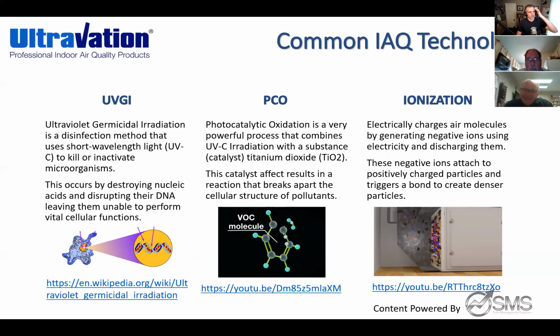So PCO, photocatalytic oxidation. We primarily use this heavily in the residential space, but it is actually available as options on our commercial stuff that I'll show you later as well. The biggest wake-up call here is a lot of people think everything's the same. They think it's UV light and you're done. Well, it is important to let people know, especially on the high-end residential, especially on the commercial, that people can amplify their air purification by adding in PCO technology. And again, it stands for photocatalytic oxidation. Long story short, you need two things. You need to have a UVC wavelength bulb, and you've got to have a surface that has titanium dioxide on it as a coating or infused into it, like on our carbon products.